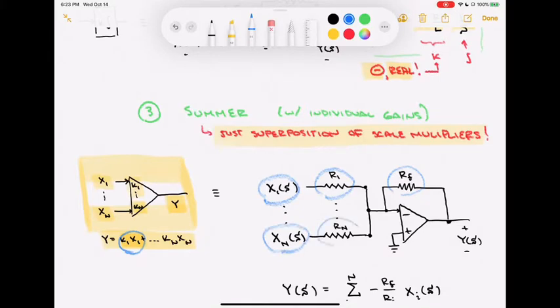and each has its own resistor in there, all these currents come in and join at that single node. And we know how currents hit a node. Currents have to sum together. All the currents going into a node sum together. So every single one of those input currents that comes together in that node sums together to make a final current that goes through that feedback resistor. That's how we get the summing action, because currents going into a combined node sum up. That's basically Kirchhoff's current law.